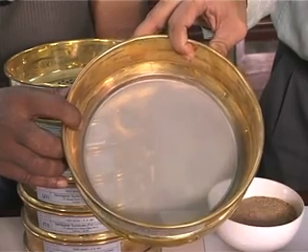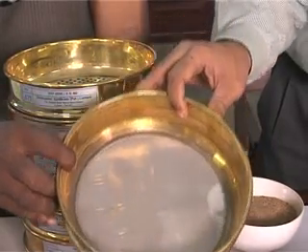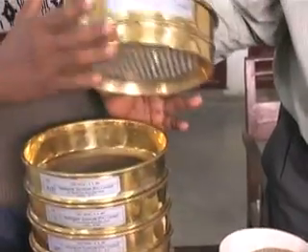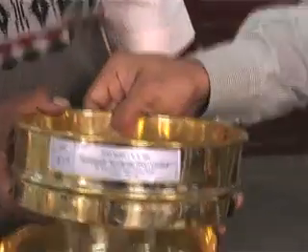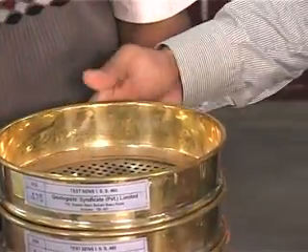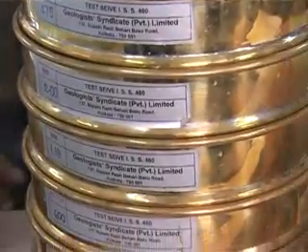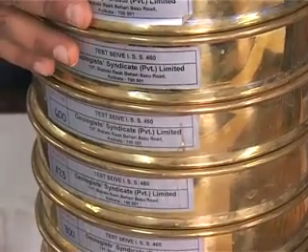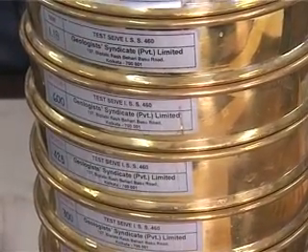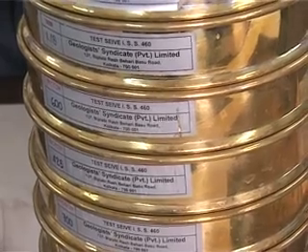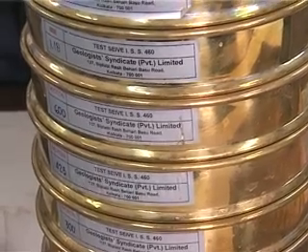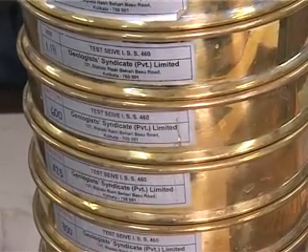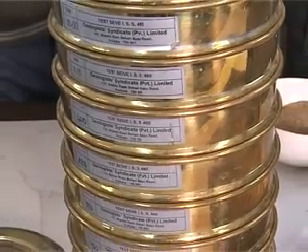This is the 75 micron opening size sieve, whereas the first one that you saw had an opening size of 4.75 millimeter, as is mentioned on the label. Now you can get the idea: looking at the labels of the different standard sieves, you can see that the size goes down starting from the top. The coarsest sieve is at the top and the finest sieve is at the bottom, and below the 75 micron sieve is a pan which will collect all the particles which are finer than 75 micron.